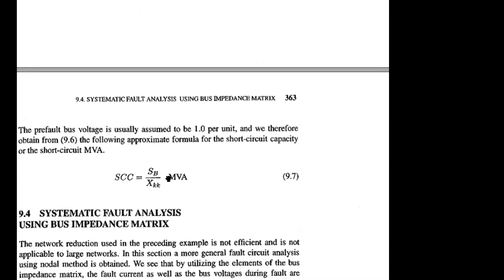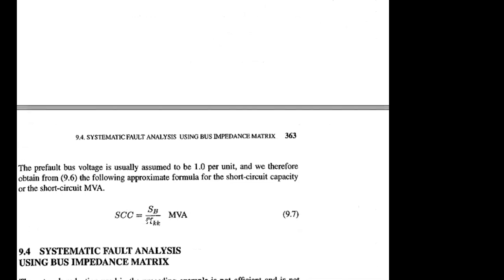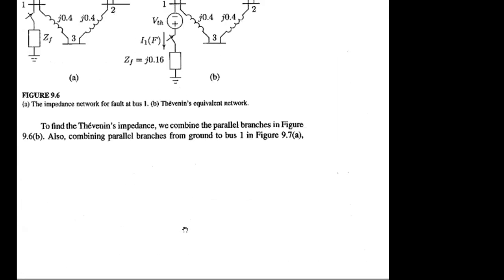That means if the short circuit MVA is given, you can apply that short circuit capacity MVA over the impedance or admittance which you have generated through the Thevenin equivalent concept by yourself. So short circuit capacity for the system will be the capacity over the impedance or admittance information. So that's the discussion all about today regarding that syllabus.